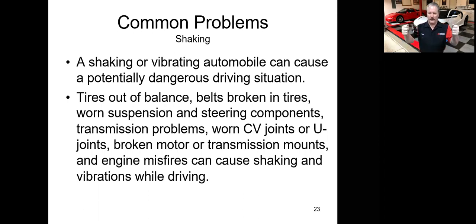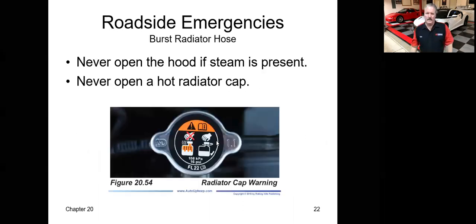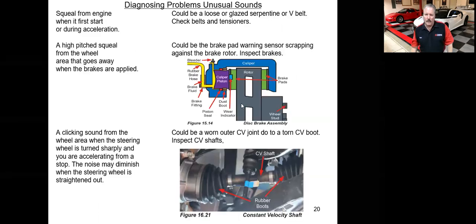If it's perfectly fine while you're driving 55 or 60 and you just start to step on the brake pedal, and as soon as you step on the brake pedal the steering wheel shakes a little, the brake rotors, which we saw right back here, this rotor right there is probably warped a little bit, and these brake pads are oscillating in and out, and that's going to cause your steering wheel to shake.